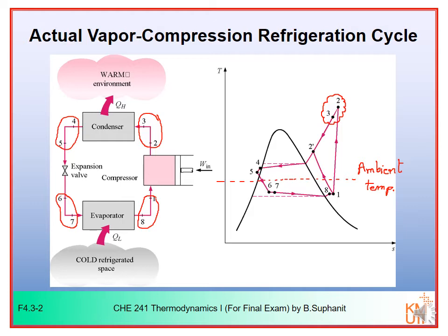While the heat loss in line 2, 3 will give benefit in terms of reduced condenser load. The pressure drop and heat loss in line 4, 5 will give benefit in terms of increased refrigeration capacity. When the liquid becomes more subcooled, it will flash through the valve and you have more liquid.